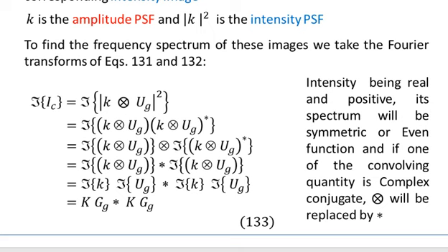In the fourth step we have written the Fourier transform of the first quantity, and here we have converted the convolution sign into the autocorrelation sign, and we have removed the conjugate, because in the autocorrelation the complex conjugate appears in the integral description of the Fourier transform. That's why we have removed the conjugate sign and converted the convolution into the correlation.